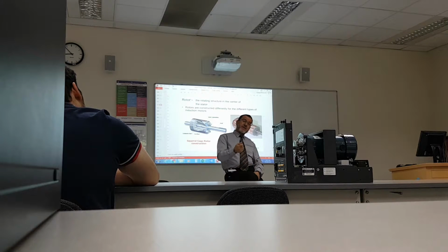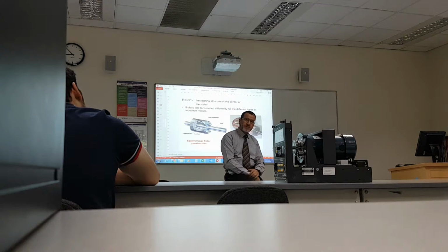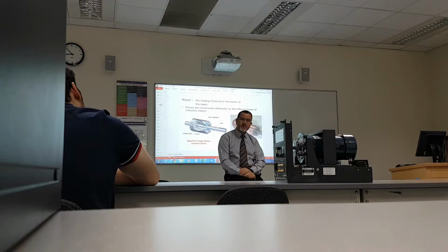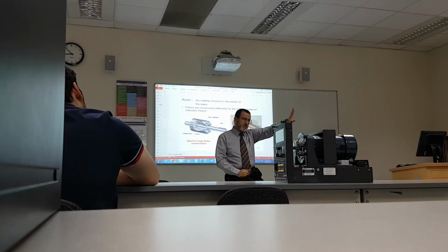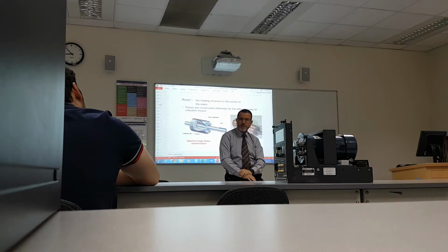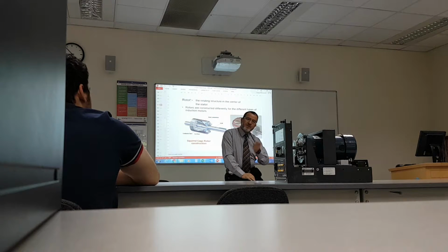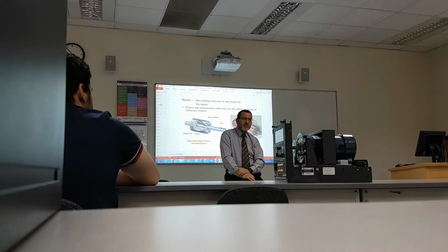And companies invest money into these capacitor banks for power factor correction. And of course, if you really want to go into the details, you have to know how much it costs if the power factor goes below 0.85, because Kahrama has a tariff for that. They say as long as you're 0.85 or more, no problem. We're not going to charge you for reactive power. But if your power factor falls below 0.85, you're going to have to pay or make a power factor correction.